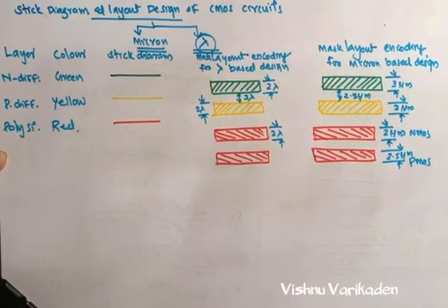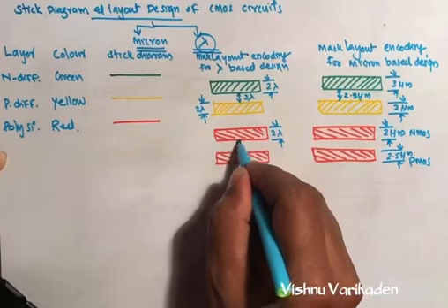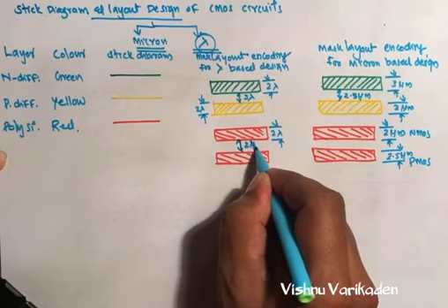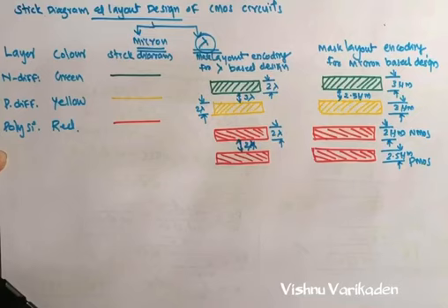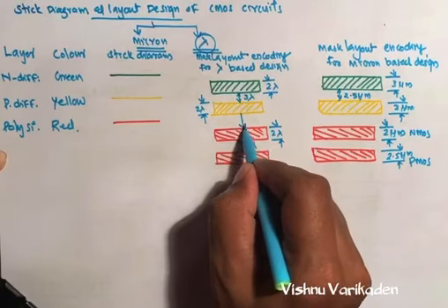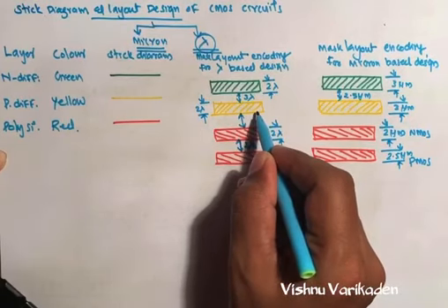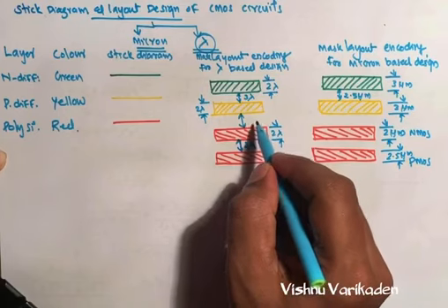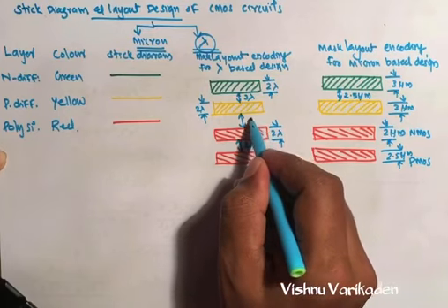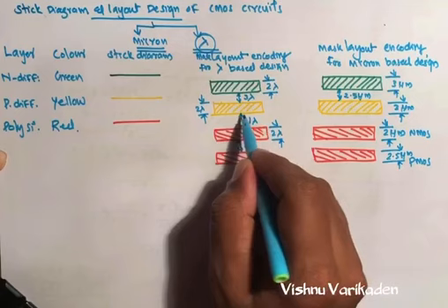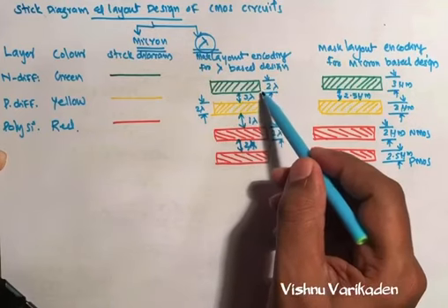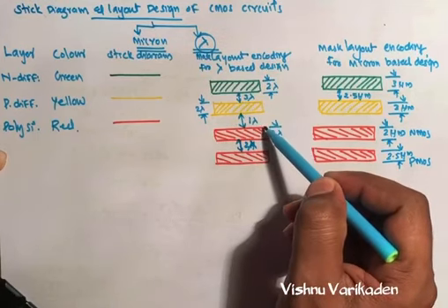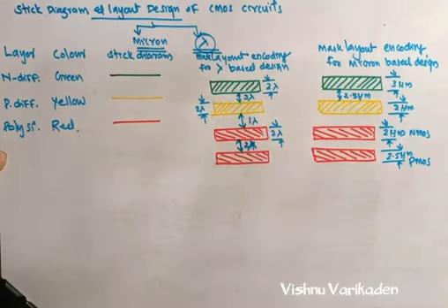Also we can make the distance between the polysilicon. This distance between is 2 lambda. From P diffusion to polysilicon is 1 lambda. Also between the N diffusion and the polysilicon is also 1 lambda only.